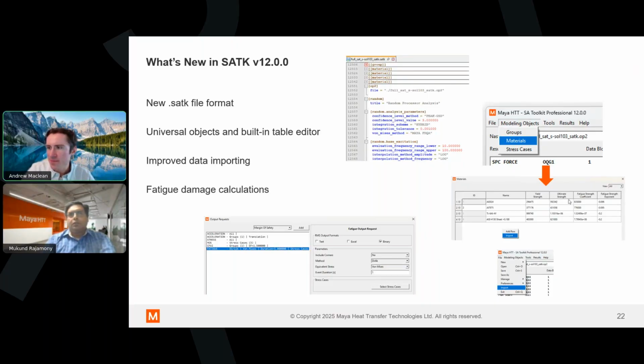There was that question on mesh refinement and the role that it plays. Yes, it does. Mesh refinement does play a very important role. I think primarily, I can say that fatigue is very highly stress sensitive, and stress is mesh sensitive. So yes, there are some guidelines. At least have 2 to 3 elements across stress concentration areas, or keep element size less than half or 1/3 of the radius on a fillet. Use solid elements for fatigue critical areas instead of shells, unless it's very thin.